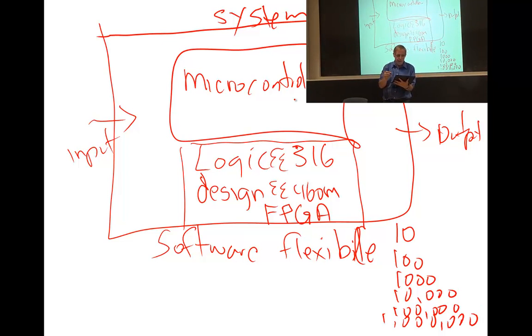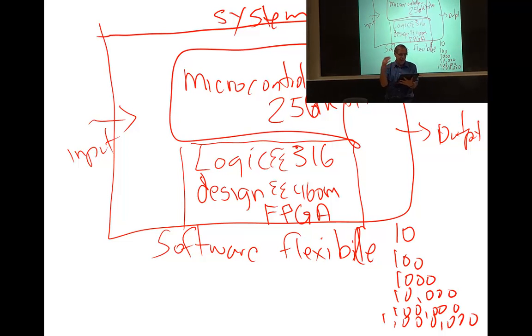There really isn't a limit. Now we, in this semester, only have 256 kibibytes of ROM. And if it takes about 2 bytes per instruction, we got about 100,000 opcodes we can put in this particular processor. But this is a little one. We could certainly put more. Okay? As opposed to digital logic,